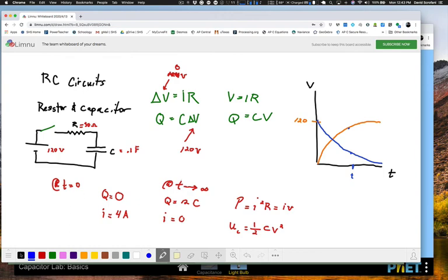And then finally, if I were to make a graph of current versus time in this circuit, I versus t, that would, let's use pink for that, that would start off at 4, as we know, and it would decay. This is exponential decay, actually, and it would decay asymptotically to 0 as time goes on. And the simulation showed that, but it showed it in the negative area of the graph, rising, kind of coming up like that, okay?